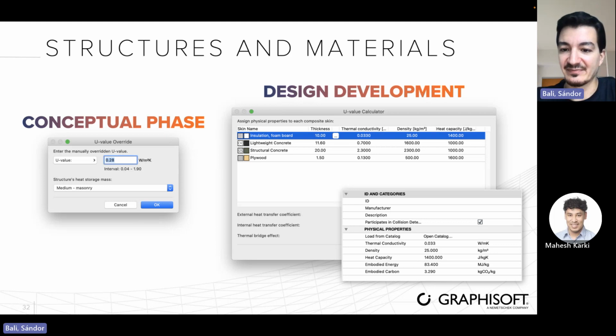We don't have to do anything about this. If we use the default building materials, then the U value is going to be calculated. So right away, we can see if the actual is going to be below or above the 0.28. If it's above, then we have to either change the thickness of the insulation or use different types of materials.